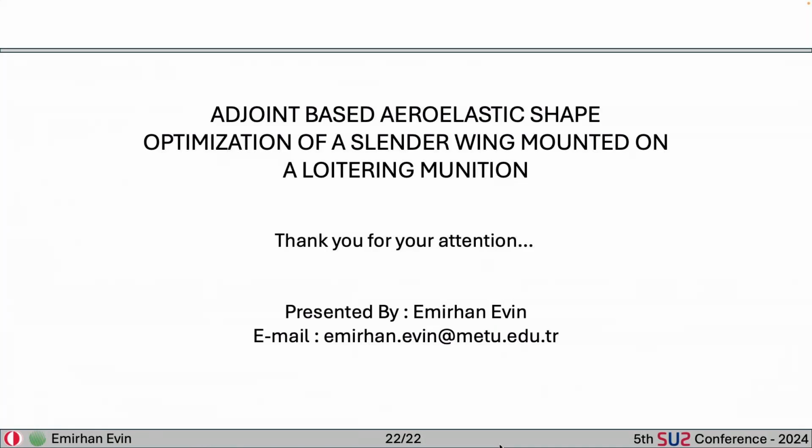But I have a question about your problem. You have an FFD box set up, then you compute the sensitivities by the continuous adjoint method, and then you get, to stay in SU2 terms, the objective function OF_GRAD file. And then you do a surface deformation, and then you get these kinks.